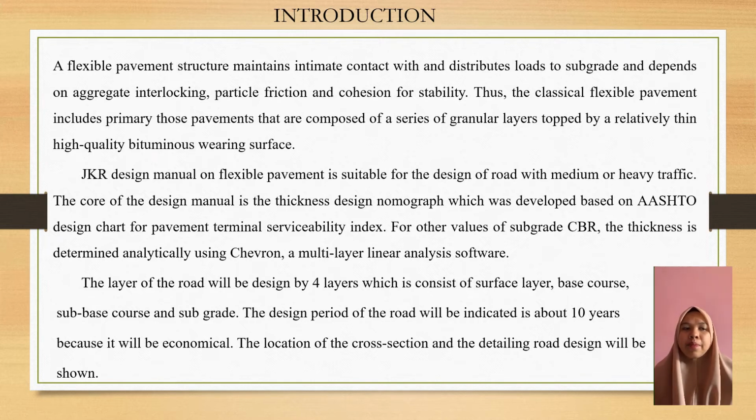The layers of the road will be designed as 4 layers, which consist of surface layer, base course, sub-base course, and subgrade. The design life of the road will be about 10 years because it will be economical. The location of the cross-section and the detailed road design will be shown.